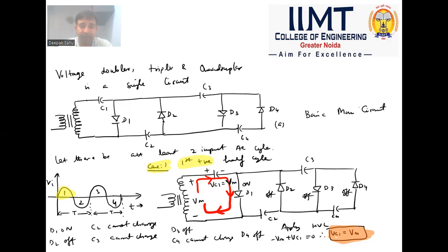So here, if we see there are four capacitors and four diodes combination, so we can easily predict that for the two diode and two capacitor systems, one complete cycle was there, one positive half, one negative. So it is obvious that in here we will take at least two cycles. Minimum two cycles are needed to charge the capacitor C4, including C1, C2, and C3.